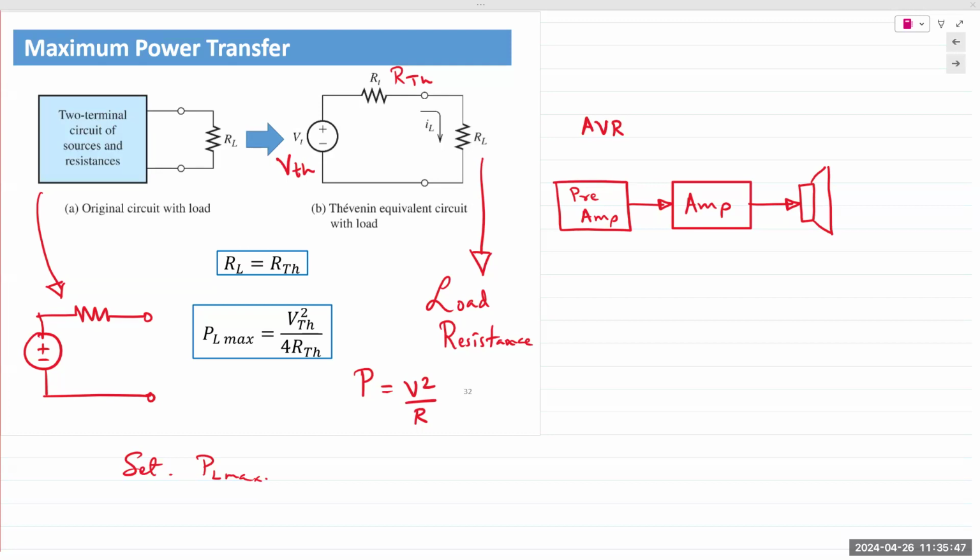Then we mark the nodes where we cut it out, we transform it outside of the circuit, and then when you plug it back in, you now have a parallel connection of a resistor and a current source. You plug it back into the circuit at exactly the same two nodes. That's how you would do it. So it doesn't matter whether it requires 2 cuts or 4 cuts. We have to keep track of the nodes and then remove it from the circuit.